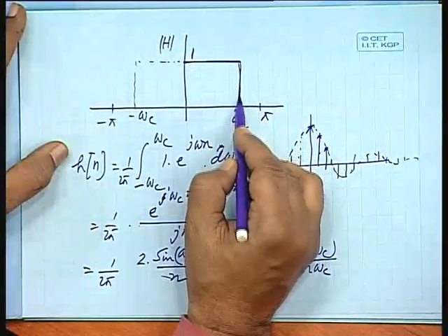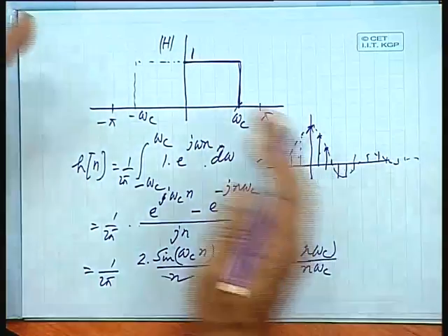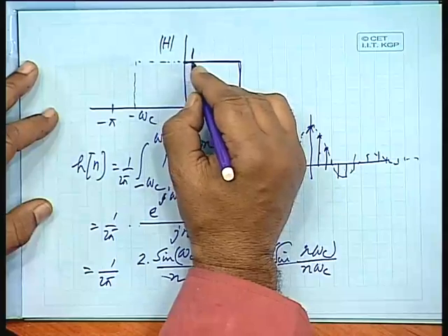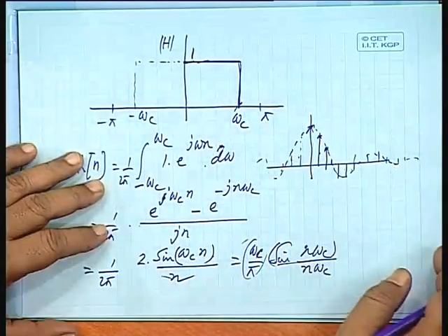I will call it h0 dashed which is equal to h10, h1 dashed which is equal to h9 and so on. So, I will get a sequence of 21 points. So, it is a 21 point sequence filter which will ensure that this is more or less approaching this. If you have a larger length, then it will be coming closer to this, that means the error will be less.